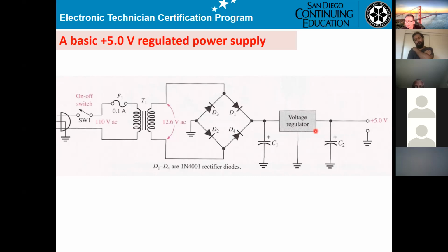Someday I will give it to you. This schematic is for the voltage regulator. That means whatever is coming in here, what comes out is going to be 5 volts. And this capacitor tries to make sure you get a straight 5 volts, not ripple. If you get a big ripple, that tells you there is a problem with this capacitor here.